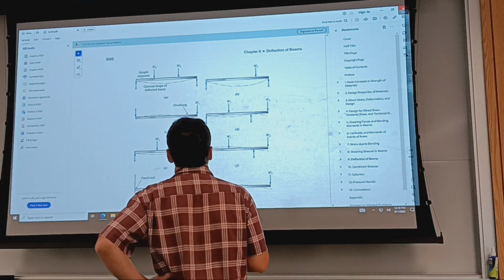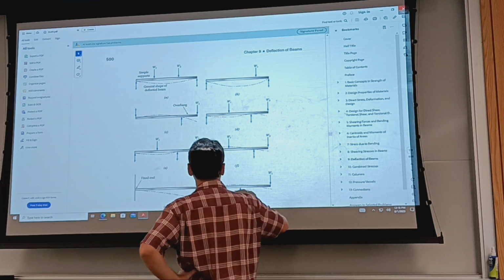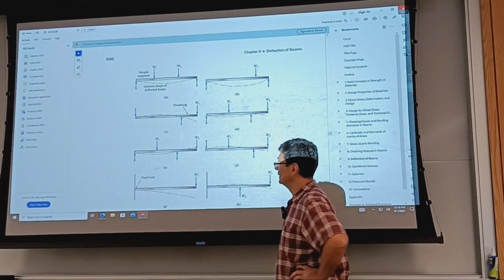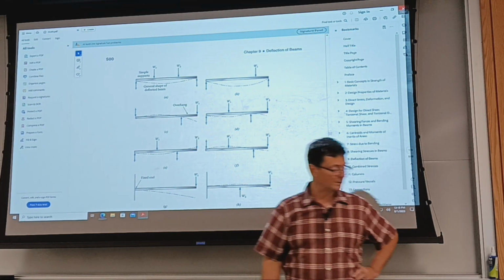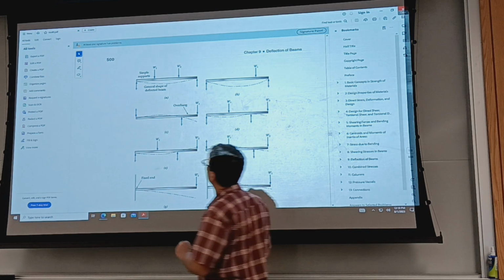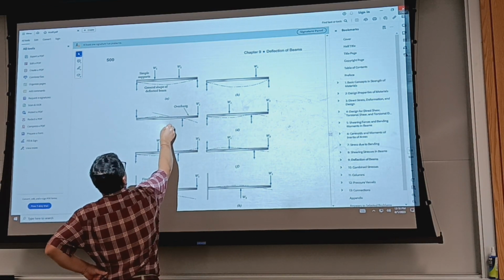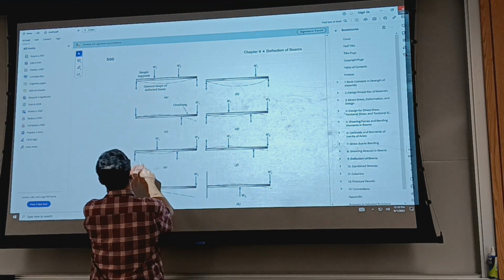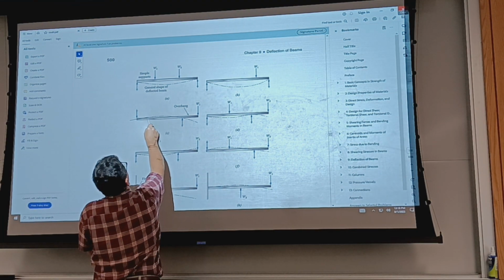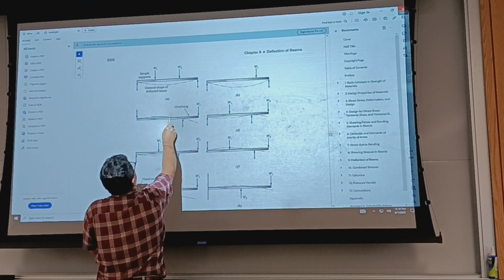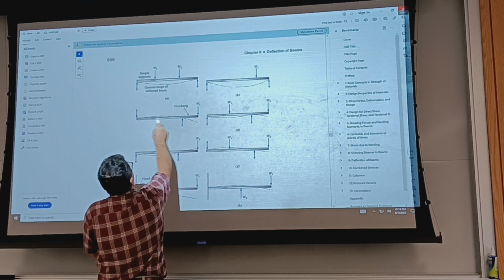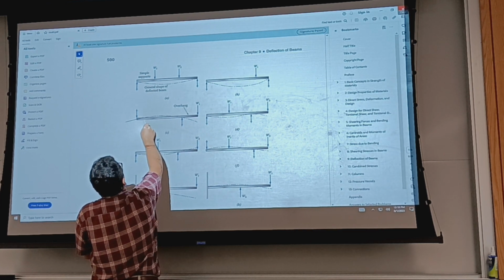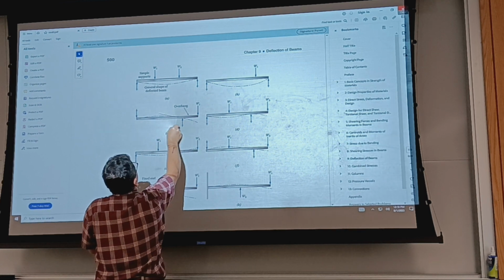Okay, so yeah, simply supported beams. And then we have what? We have the cantilever. It's a fixed end. And something that I should mention at this point: we have the tangent to the beam. Let's say this extends. You have the tangent, which follows. The tangent is 0 here, and it goes to a negative value coming from a positive. But it starts here at the support with a non-zero slope, the tangent to the curve, okay?